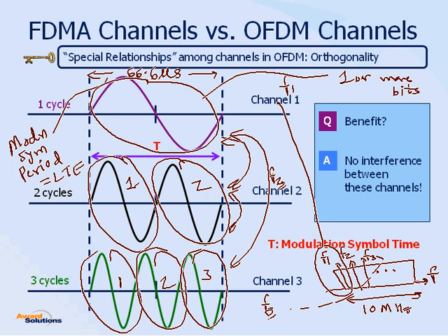That is that. Now, what is the frequency of this subcarrier? So you have one cycle here, so the frequency will be 1 divided by T. So 1 divided by 66 microseconds, 66.6 to be exact. That will give you 15 kilohertz.